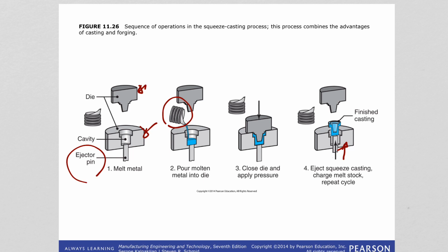Of course, here the pressures that you need to apply are much less than the forging process that we know, where we are basically working on a solid metal. This technique can be used for ferrous and non-ferrous alloys, aluminum, magnesium, and is mostly used in the automotive industry, for automotive components.